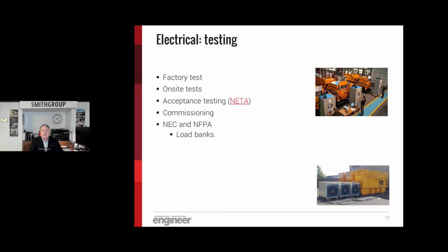Commissioning is functional performance testing. Rather than looking at, say, if the right fuse is installed, the commissioning agents will run the systems through their paces. Most often, the common thing you think about is a pull the plug test. Everything's installed, the generators are in, the facility's almost ready to go. You turn it on and someone flips the switch, turning off the utility, and watches at various points in the emergency and standby systems to see if the load functions.